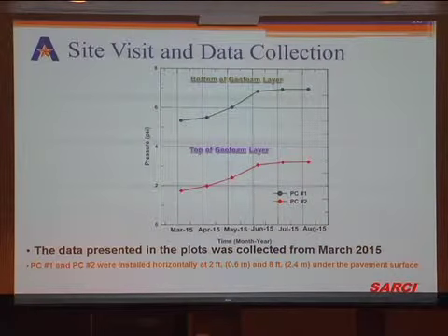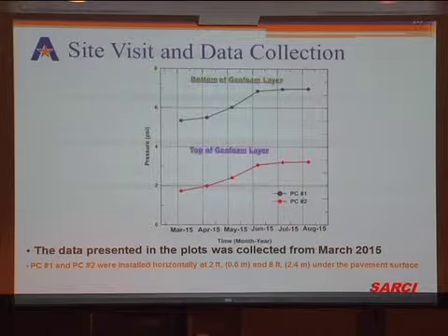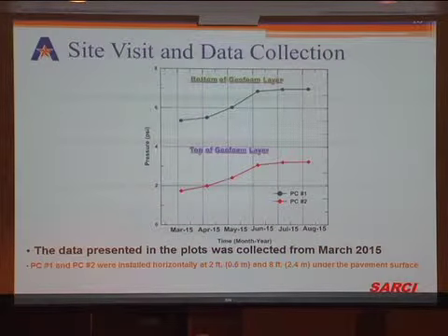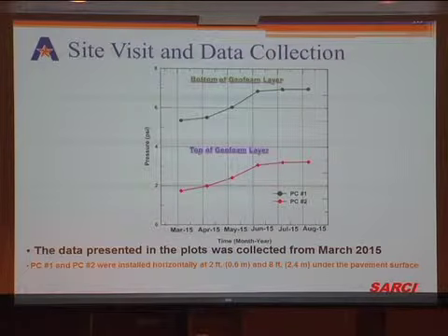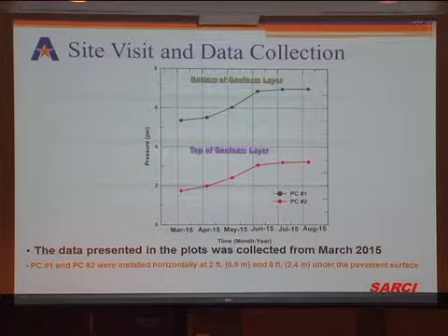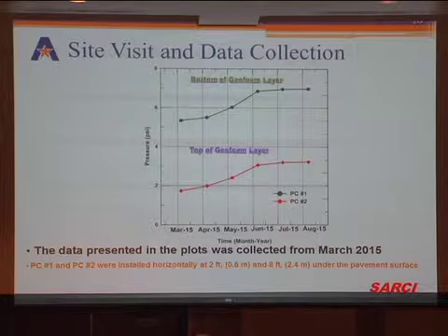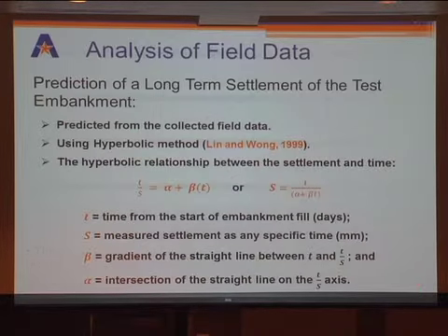showed the amount of PSI, which is, again, a small amount. And the foam itself will absorb a lot of the stresses coming from your load. So the foam itself will capture it, so the amount of stress it will transfer to underlying soils is much smaller. That means the stress on the subsoils underneath the foam is going to be smaller, so settlements will be smaller. And that was the whole approach of why the foam is used. Foam itself will capture some of them.